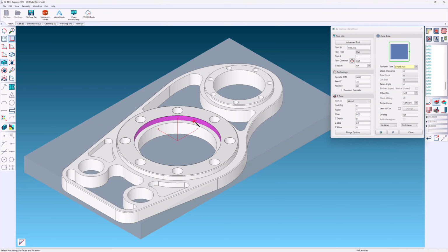We may have selected the vertical surface for this feature, but CAD-CAM recognizes that it should not violate the surface below. We'll apply a multi-pass, adding stock to the wall of the contour, allowing us to take smaller steps as we creep up against the wall. I will share a tip. We can take the total stock and divide it by the number of passes we wish to take. This is possible because every dialog is a calculator.